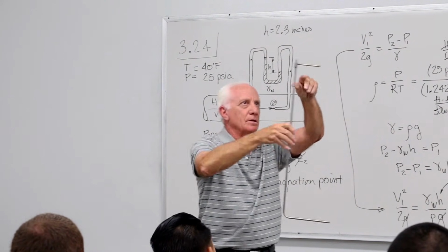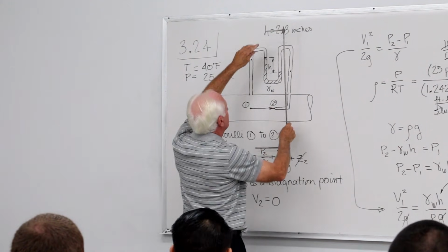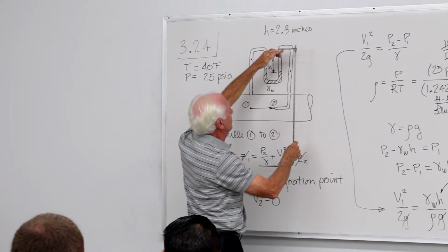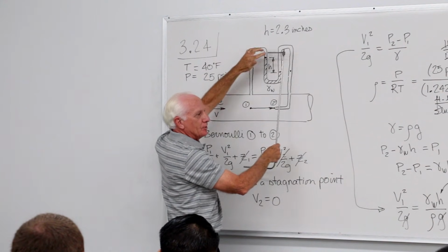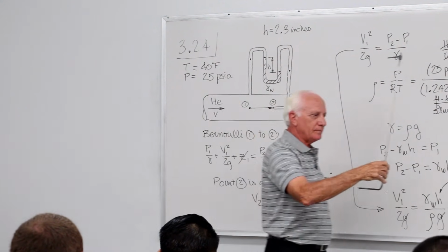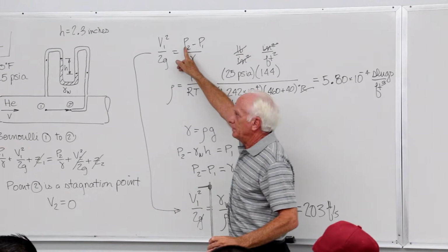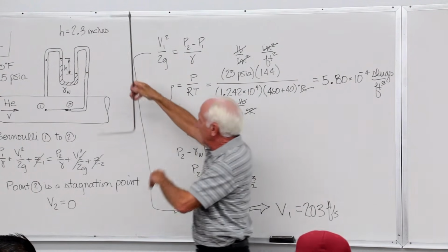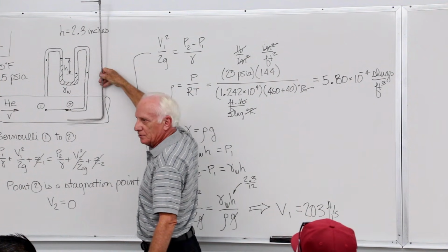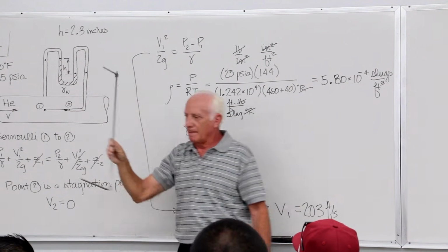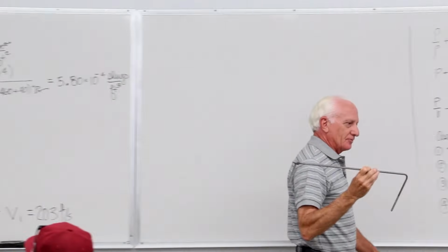Put this one in a duct. The high pressure goes over here. The low pressure goes over here. Put it on a U-tube manometer, and then measure that delta P. Measure delta P, put it up here, and find the velocity anywhere you want in the tube or the duct, like this. Put it anywhere you want. So these are used frequently.